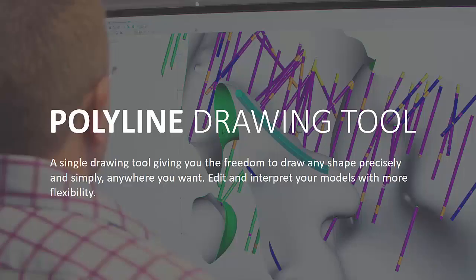Leapfrog has a powerful drawing tool that gives you the freedom to draw any shape simply and precisely anywhere you want. This single drawing tool can be used to create new surfaces or edit existing ones and is used anywhere line work is able to be drawn in a project. It is very flexible and allows you to create straight or curved 2D or true 3D polylines as well as single points. The tool has options to control the pitch of the surfaces by adjusting a line's ribbon orientation or by adding points with normals.